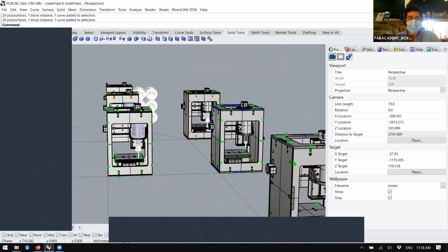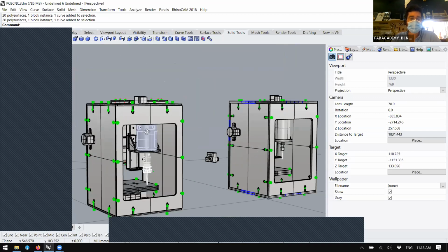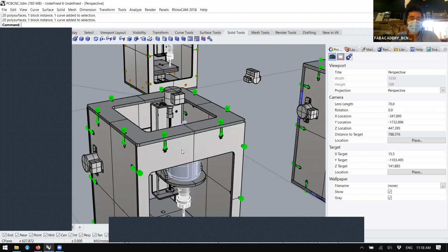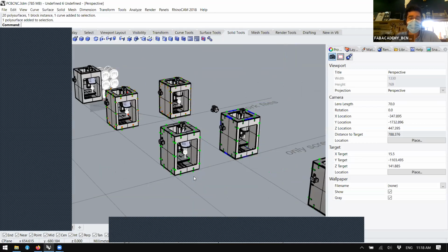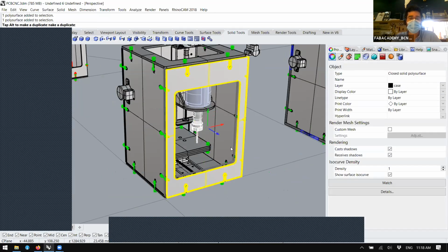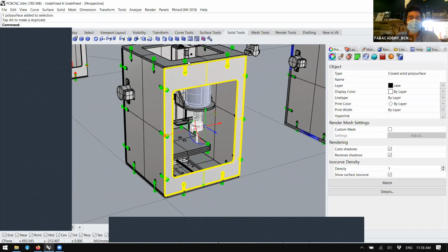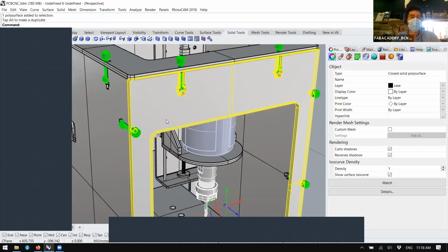When you have this kind of basic design, okay, we have the screws for fixing. What can we have now to make the assembly easier? Putting this plate and fixing it with 2 screws, there is no constraint that will keep the plate from sliding and moving.